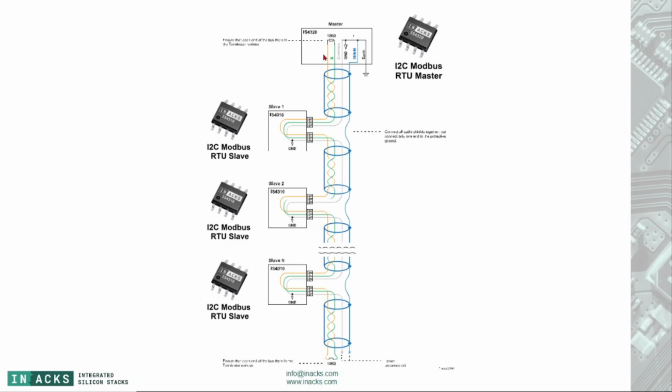This is a typical, more general Modbus bus implementation using a Modbus Master chip and Modbus Slave chips. You can use a PLC or a computer here. You can use any device as a slave. It's Modbus, a standard protocol. Use any device that you want as long as you match the electrical layer interface, the baud rate, parity bit, and stop bits, and only the address is different. Don't put 2 slaves with the same address.